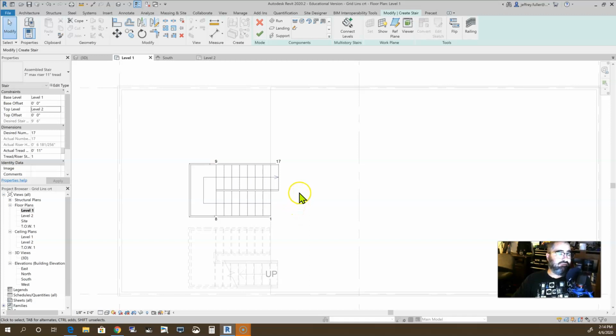You can do that with a left run. So again, if we're going to create another set, okay, so we did a right run, you could do a left run. So basically, you have run left, run center, run right, and then you also have exterior support right and exterior support left. And that would be drawing using the stringers, which are underneath the stairs that provide the support. It will be using the left and the right of those to create your drawing.